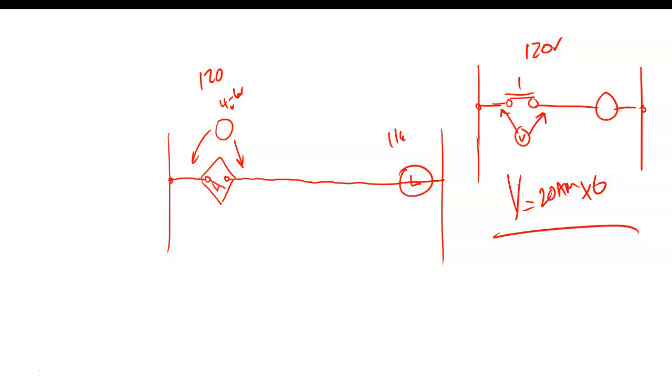So we're going to get into trouble using a lot of solid state 2-wire sensors, because if I came over here and tried to put another one in series, what would happen? It's going to drop an additional 4 to 6 volts. Now we're dropping 12 volts, right? You understand that? So we have to come up with some type of scheme on solid state sensors. You don't usually use multiple solid state sensors in series if they power through the load, because they have to drop a voltage, right, even when they're true. Everybody okay? Does that make sense?